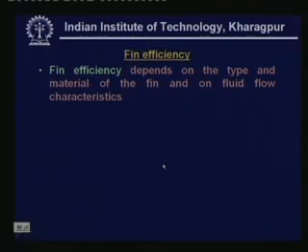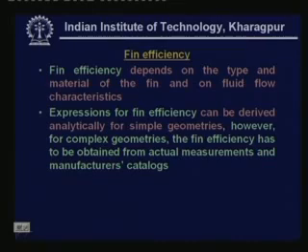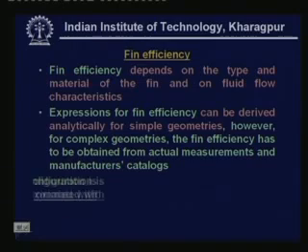In finned heat exchangers we have to find the fin efficiency. Fin efficiency depends on the type and material of the fin and on fluid flow characteristics. Expressions for fin efficiency can be derived analytically for simple geometries. However, for complex geometries the fin efficiency has to be obtained from actual measurements and manufacturers' catalogs.